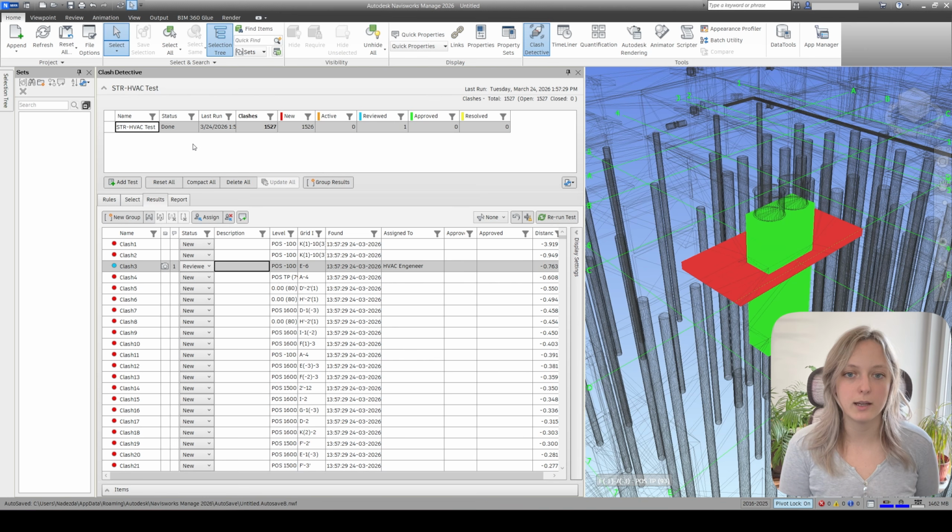So in order to have fewer of these clashes detected, you should first just browse through your model and kind of see and resolve those big clashes, and then activate Navisworks when you want to actually check out those smaller clashes, because that way you do not get this giant number of clashes, but you actually get this number to be a little bit smaller, and you have an easier time that way.